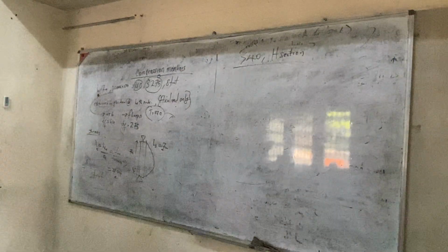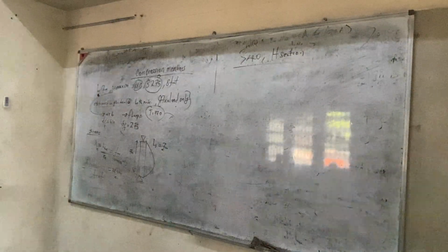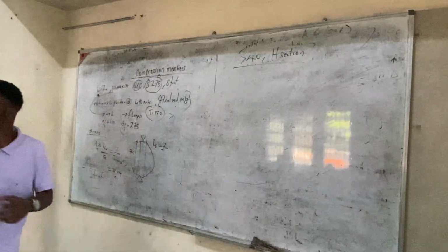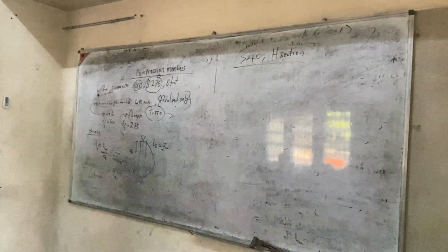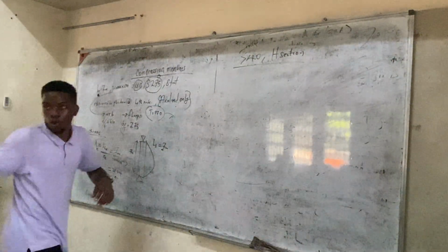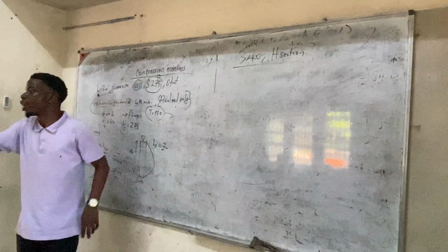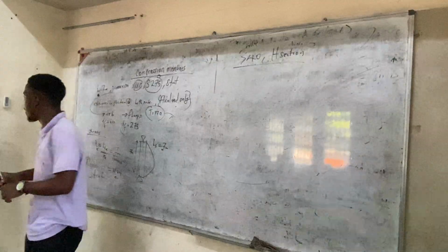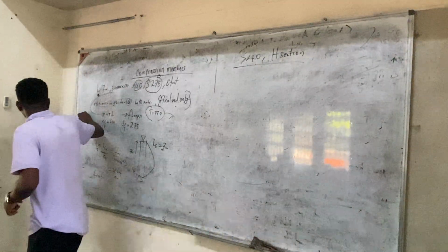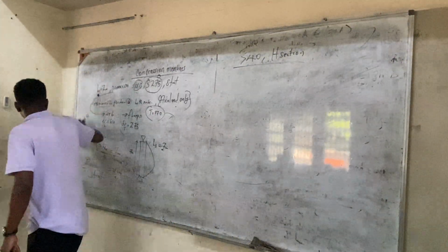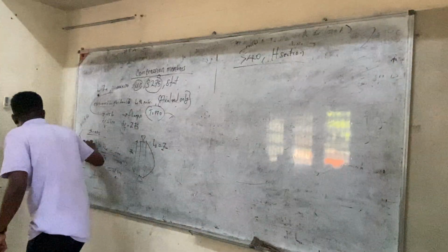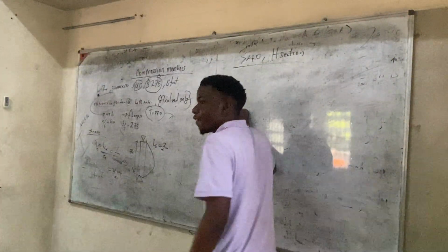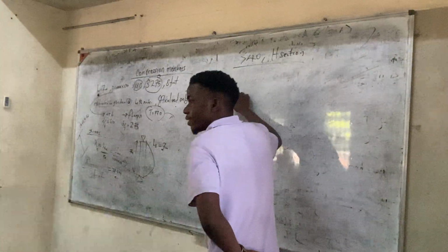Yes. One word: manufacture. Because we're using universal column and beam. So your question, why is it H section? Check your section tables. You will see that for beams, you'll be having 1000 by 500. That's obviously a dimension like this. But in H, you'll be seeing something that is very, very close. That is the flange dimension.